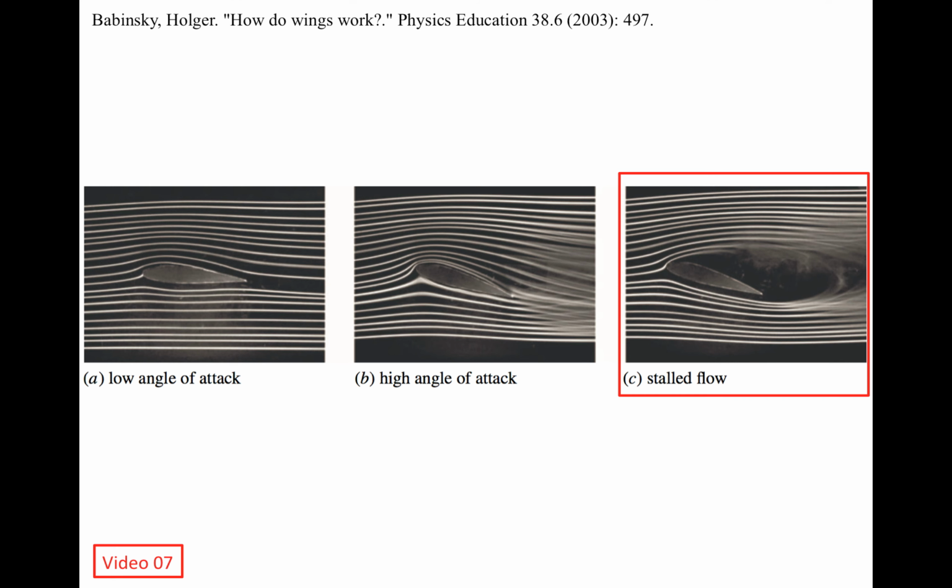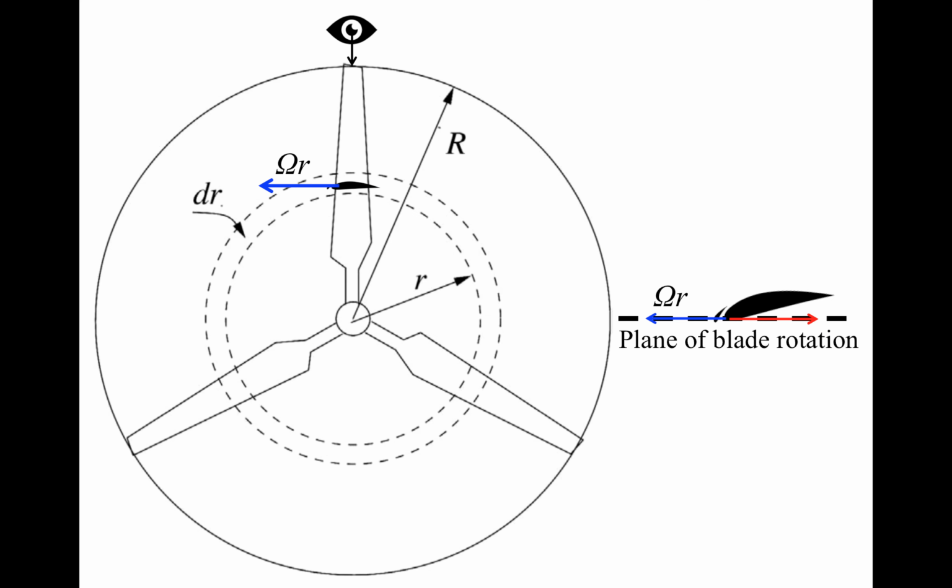We are deliberately changing the pitch angle using the pitch control system. And the stall induced using this kind of scheme is called active stall. For wind turbines that do not have a pitch control system, for example, small wind turbines with fixed blades, you cannot turn the blades. It is still possible to use stall to regulate the aerodynamic torque above the rated wind speed.